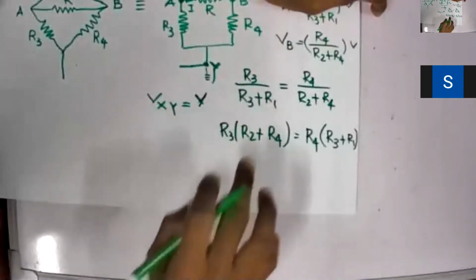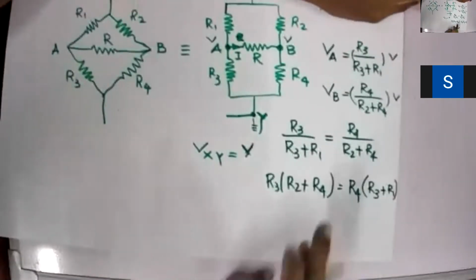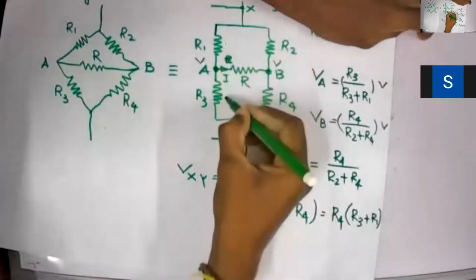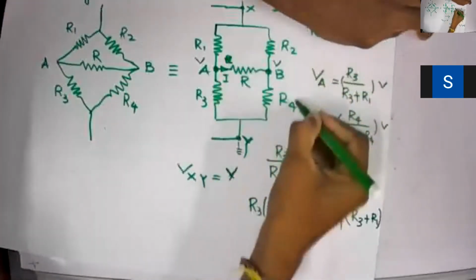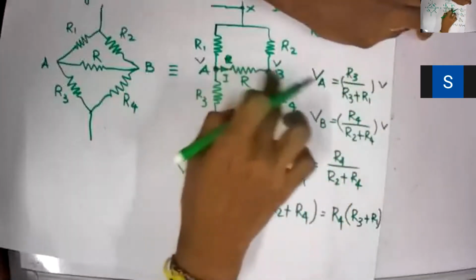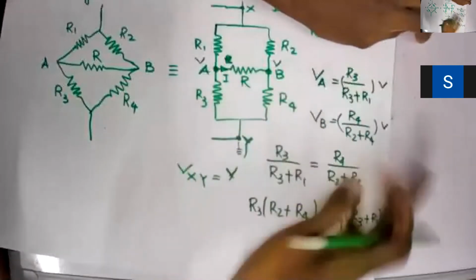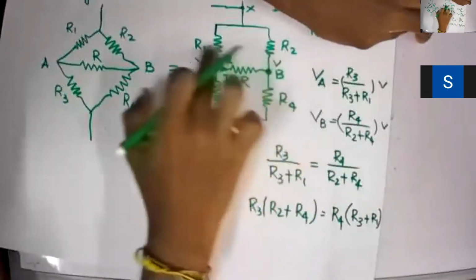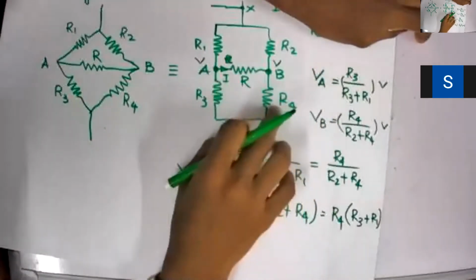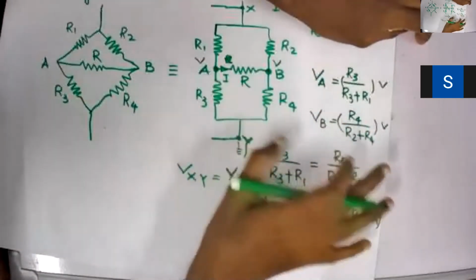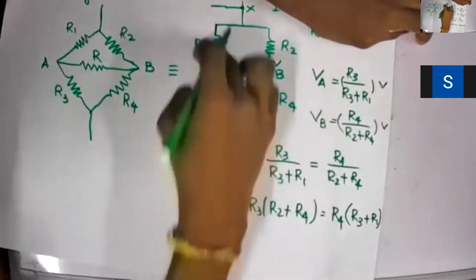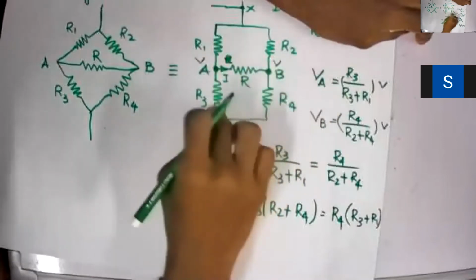Clear, right? So from this one we can derive that, if these two ratios are equal to the ratio of this one, right? So 1:10 means 1:10, then the voltage at this point is equal. Or in other words, if this ratio is equal, R1 1:10 and R2 1:10, then the circuit will be balanced. But remember, you cannot cross over, either this way or the opposite side, right?